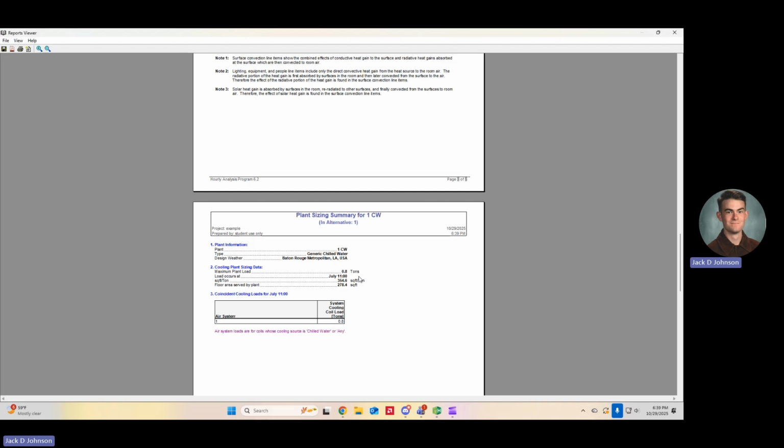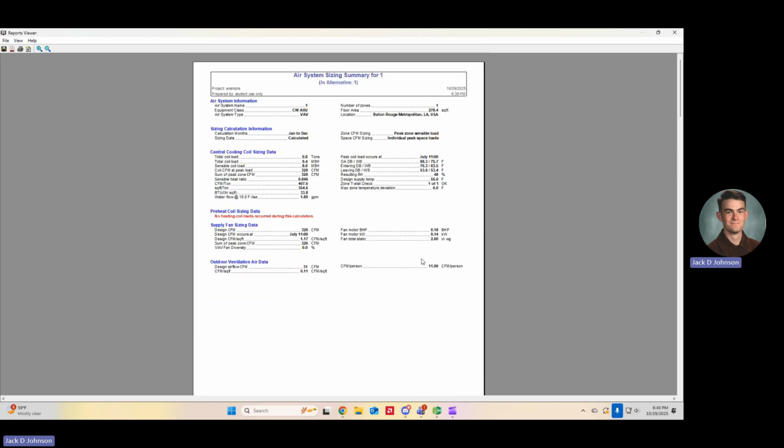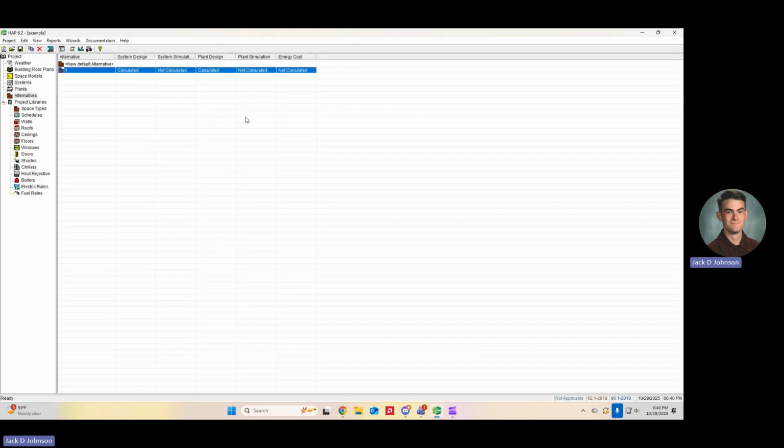We're going to go to square foot per ton, and realistically, this is a number you can probably use. So your square foot per ton reading should be no more than, call it 450, no less than 250. This is a pretty sweet spot usability wise. So you close out of that, and for this project, it's space 1, 2, 3, 1, 2, 2, 3, and 1, 2, 3.